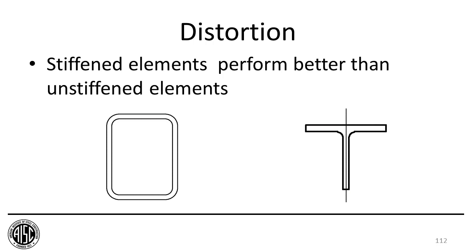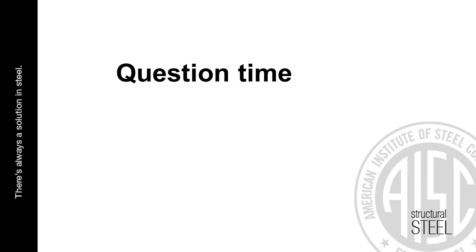That's another topic that's discussed in the design guide. It's similar to the last question, in that there's not really a real answer, because it's dependent on the residual stresses that are in the member. The cold bending methods are a good bit higher than the induction bending residual stresses. Once you dip it into the galvanizing, it's going to release those residual stresses and change the shape of the member.